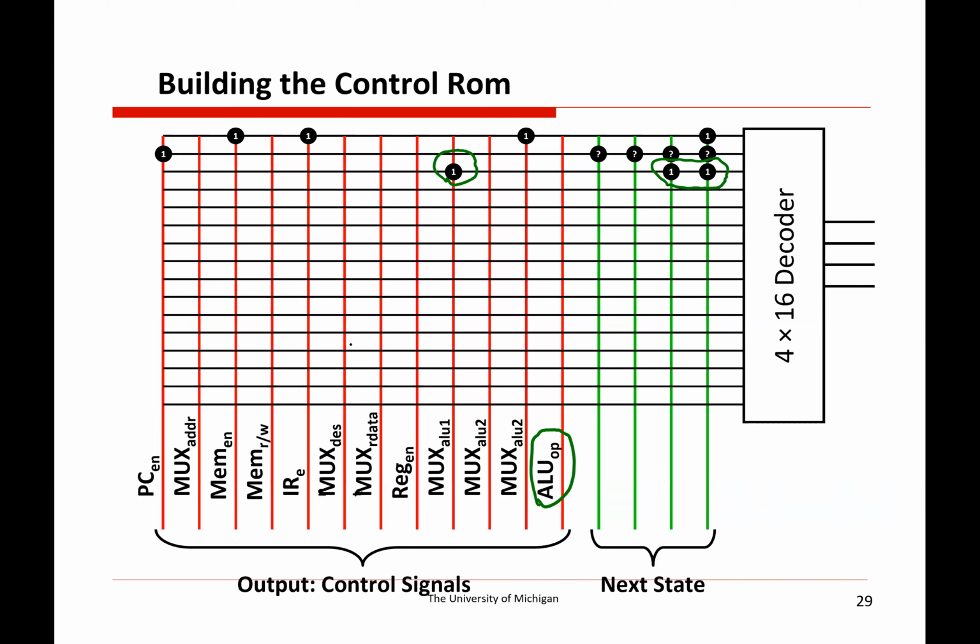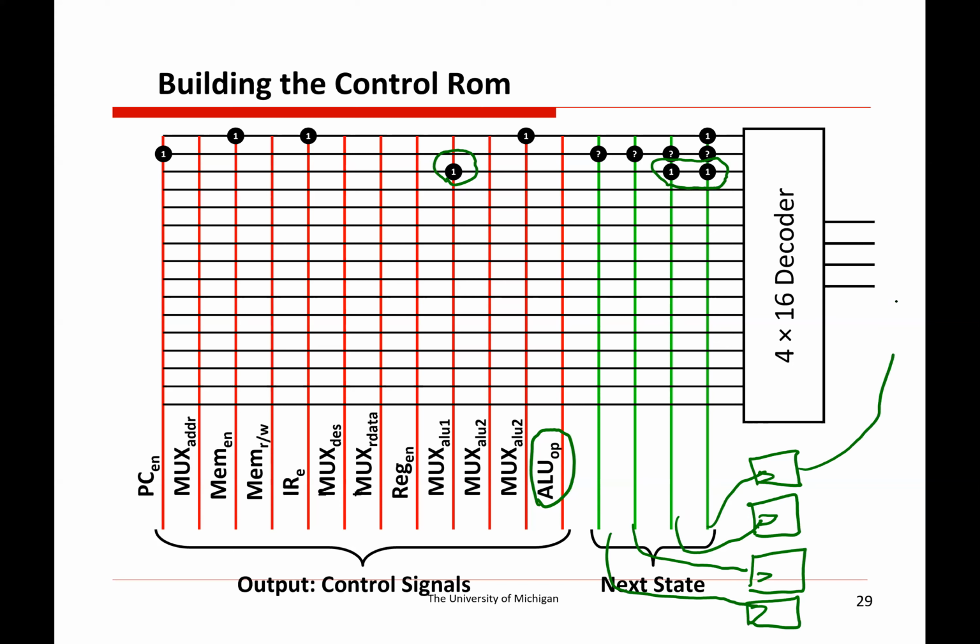Yeah, so the next state result is going to be outputting the binary encoding of what the next state should be. We're just going to have 4 flip-flops here that are holding on to what the current state is. So this one goes here, this one goes here, this one goes here, this one goes here. Every clock tick, we're remembering what the current state should be, and then we're just looping this back up into here. Except actually do the right ordering of that.